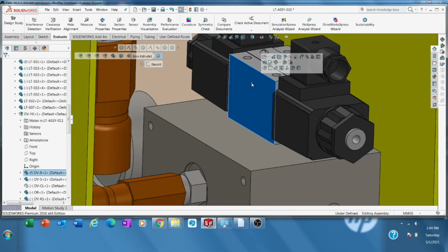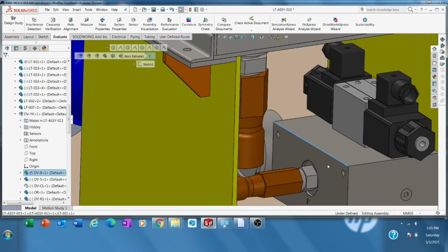Maybe in your designs it's not directly connected to the directional valve, maybe it's connected first to what we call a PRV, pressure relief valve, so you can make the system adjustable to the load you have. But that's a bit not simple anymore, a bit above simple, but not advanced. Okay, let's concentrate our time here first. So this is the manifold.